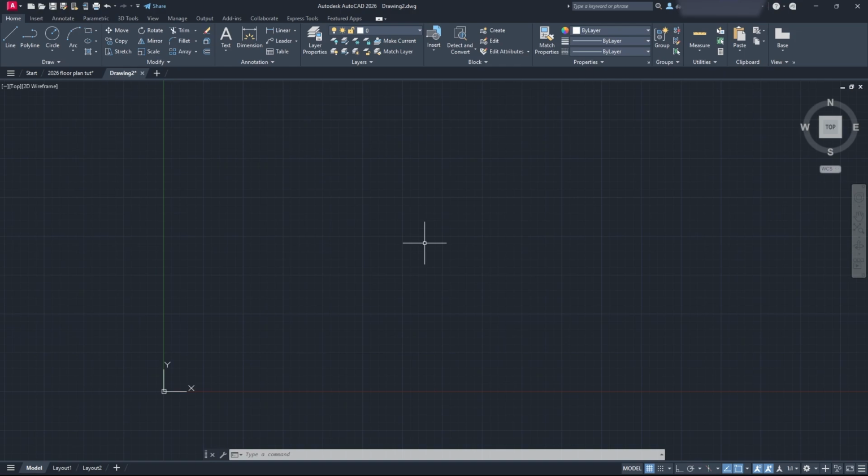So we're in AutoCAD. First thing you want to do is go to your command bar and type in units. Or, again, if you want a quick way of doing this, I say this in a lot of my videos, go to your command bar, type in DYNMODE, press enter, and then it's going to ask you for a new value right down here. So you can see enter a new value. Mine's 3. Set yours to 3. Now you can just start typing commands into AutoCAD without having to click the command bar or click the actual commands themselves, like line. So I can type line and I can start drawing.